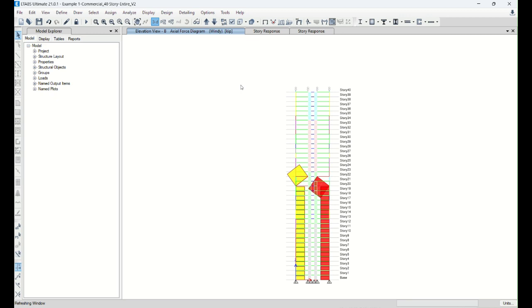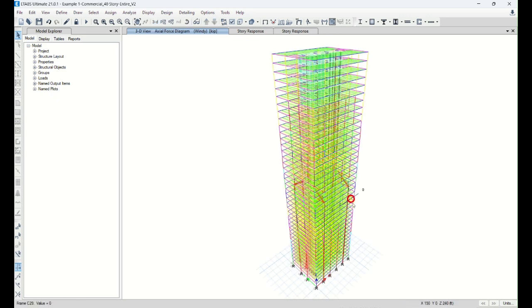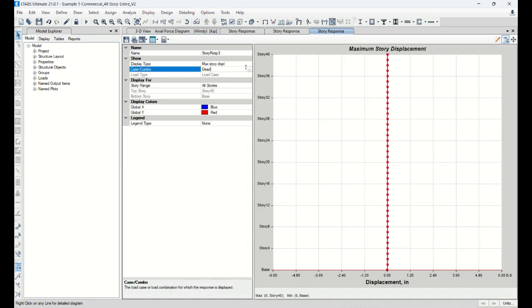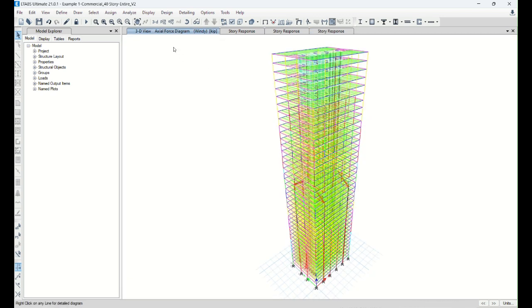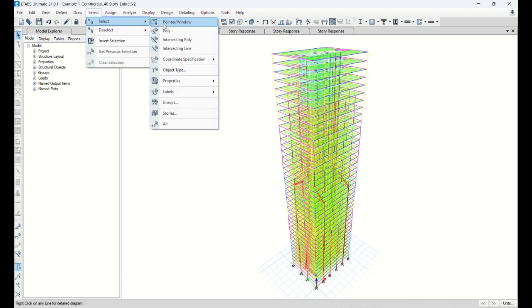I want you to first update your model and also include your lateral deflection study, right? If you happen to choose some initial sizes, you may see that the overall deflection is reduced. But you can design the bracing as well.